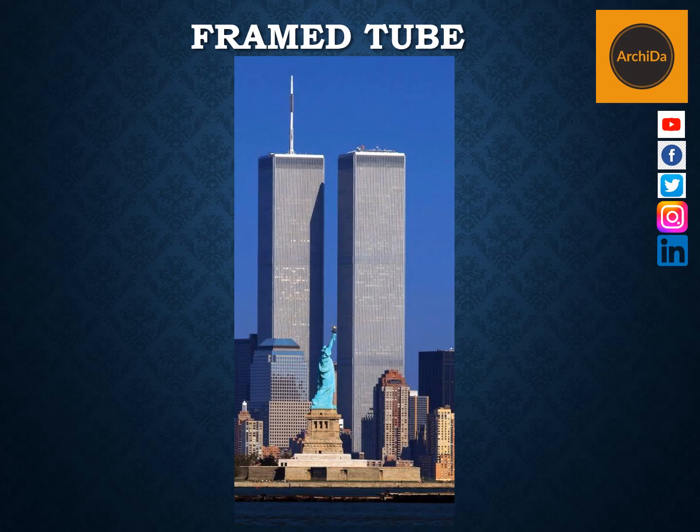Depending on the structure, the spacing of the columns is quite close, generally 1.5 to 4.5 meters, while spandrel beam depths can range from 0.5 to 1.2 meters. One perfect example of the frame tube is the former World Trade Center in New York.